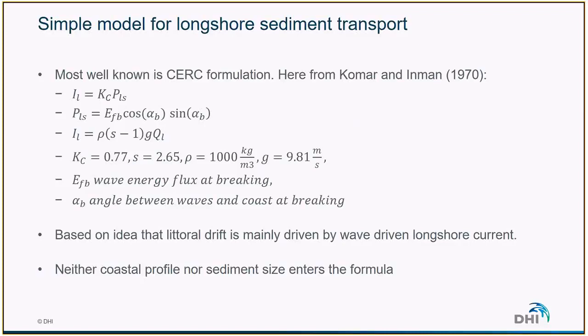It's based on the idea that the littoral drift is mainly driven by the wave-driven currents and not by tide or ocean currents. It's important to note that in this formula, neither the coastal profile nor the sediment size enters the formula, for instance. But still, it's able to provide a good estimate of the longshore transport within an order of magnitude.